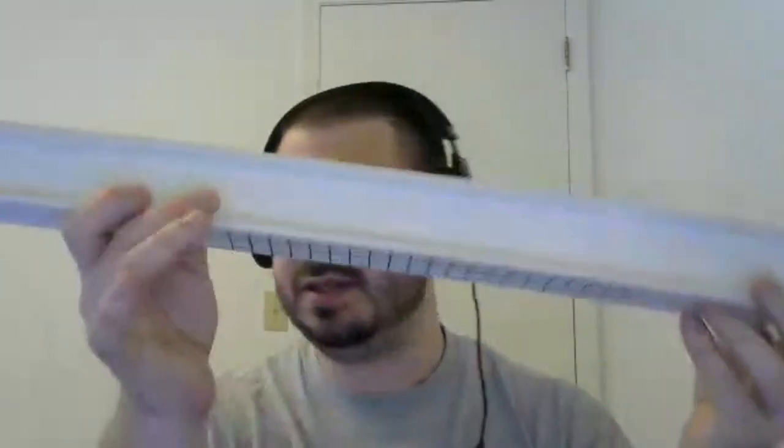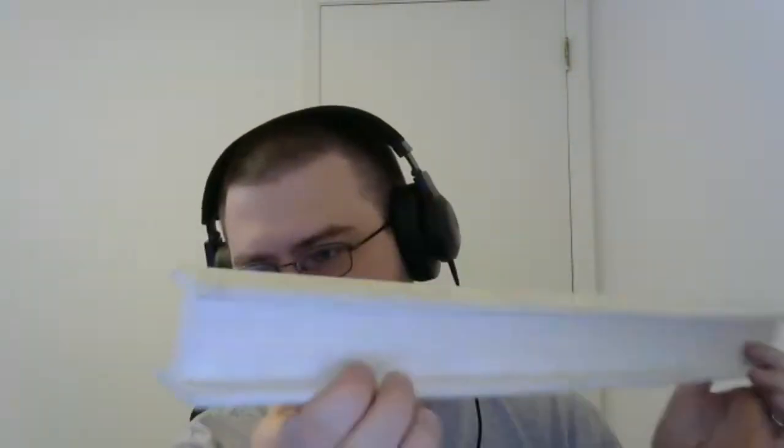Okay, good. So here I have a beam, and let's just say for the sake of discussion that this beam is, I don't know, 3 feet long. I know it's a little shorter than that, but let's just say it's 3 feet long. A brace is any device or any structure where its purpose is to prevent the beam from moving left to right when it wants to buckle. So in other words, here's the beam. Any device that prevents it from going this way laterally, that's going to be a brace.